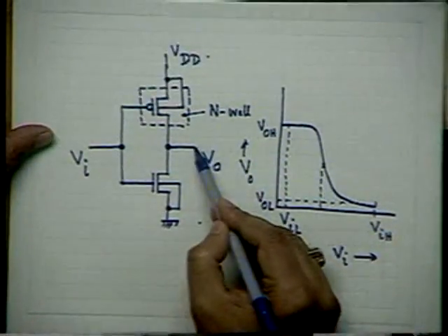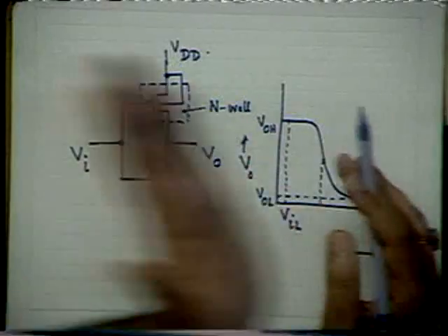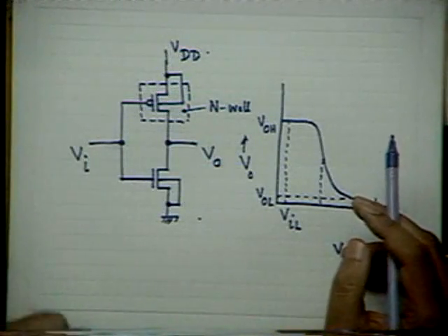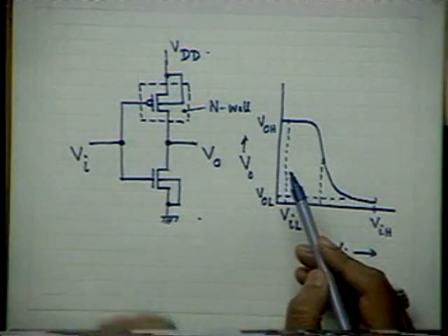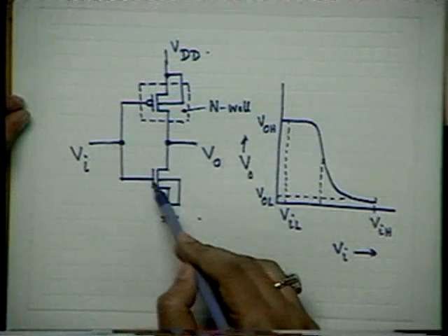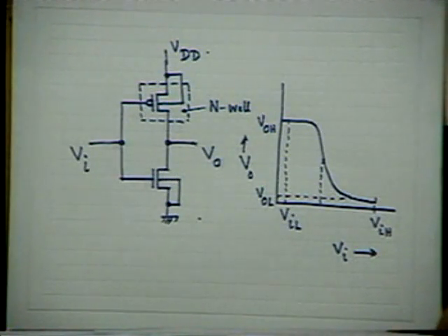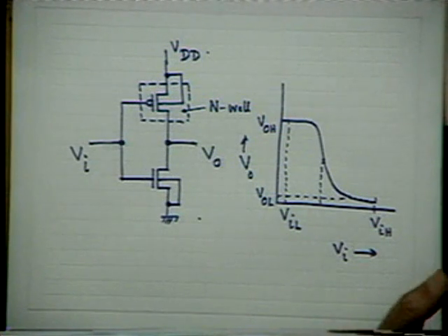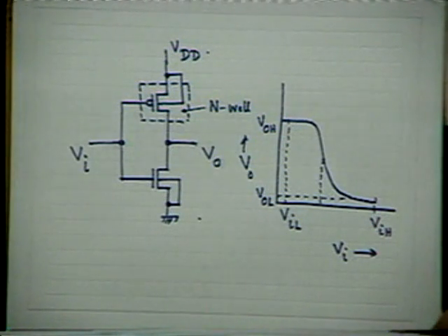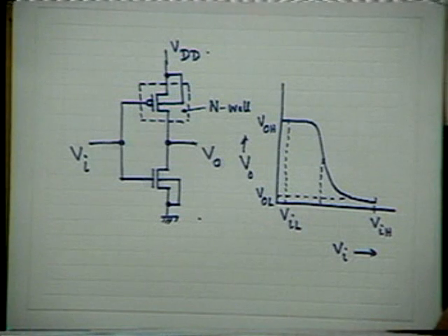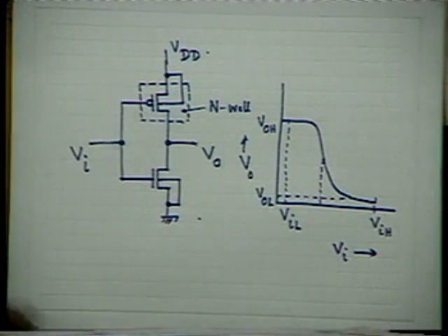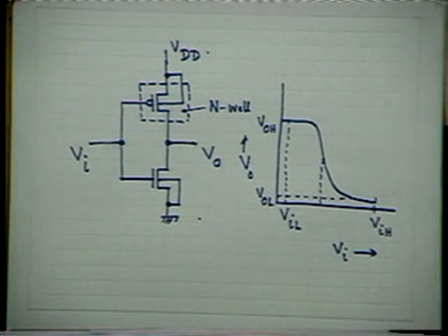The node here is connected to another such CMOS inverter. The charge stored at the input gate of that inverter discharges through the driver transistor quickly. You know that in the steady state, power consumption in the CMOS is practically zero, negligible. Whatever power consumption we normally encounter in CMOS logic is during the transition.